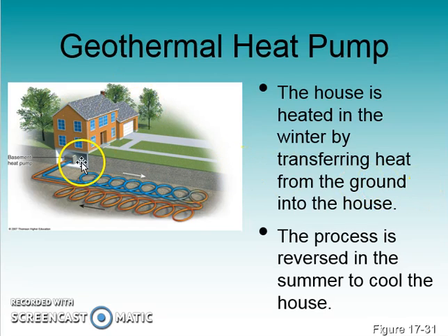So what can happen is if you put your house on a heat pump, this basically pumps water through the house, and in the winter, the water would get warmer to 60 degrees. In the summer, it would get cooler to 60 degrees. And then that would come back in, be radiated through your house, and would help heat or cool your house. You probably won't heat or cool your house to the point you want, but then you'd only have to use your heater or air conditioning for that tiny bit of difference, rather than doing the whole thing. So rather than heating your house from 30 to 70 degrees, now the heat pump would heat your house from 30 to 60, and then you'd only use your heater to go from 60 to 70.